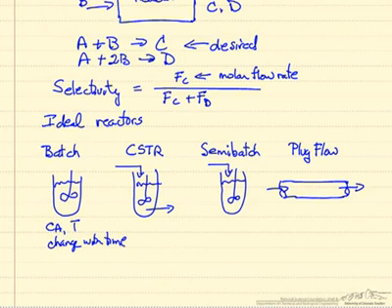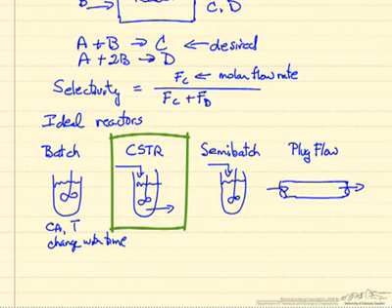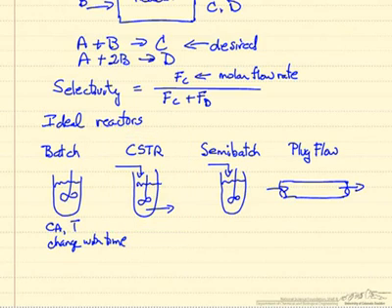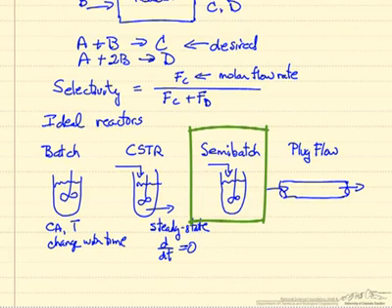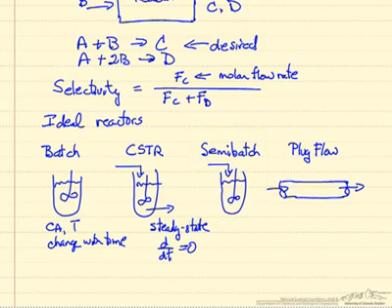So this is not steady state. We dump in all the material at once and then carry out reaction, so a closed system. A continuous stirred reactor is really quite different. It looks like a batch reactor where we're continuously adding and removing material, and this changes things quite a bit. So one means it can be run continuously at steady state, which means the derivatives with respect to time are equal to zero. We'll talk a little more about that. And then semi-batch means a batch reactor where, for example, we might add one component like A and then continuously feed in B, and reaction now again is not at steady state.